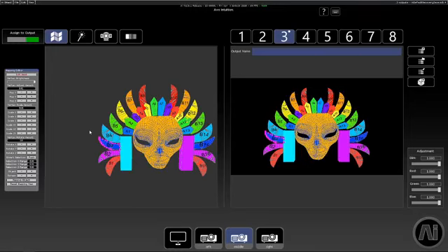And I've got a few options here. I can use these buttons here on the left to adjust position. I can adjust scale on 1 or 2 axes, and I've also got rotation, full 360-degree rotation, or in technical terms we call it 6 degrees of rotation, meaning that we can go forwards and backwards on all 3 axes, X, Y and Z. I'm going to bring this component over to the edge a bit just so that we can manipulate it, and then I'll show you sort of changing position and rotation and that kind of stuff. It'll be easier to see.